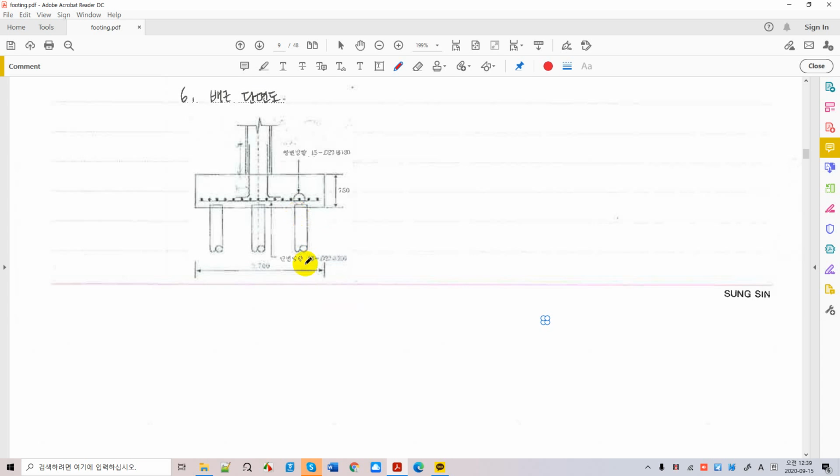If your soils are very stiff with high SPT values and high cohesion and friction values, it is favorable for having the pile capacity at the shortest depths. Otherwise, you have to go deep into the foundation soils to get an allowable bearing capacity on one pile, right? This is very important. And this is something that we really don't learn in school, but you want to take a look at it and get familiar with these practices, right?